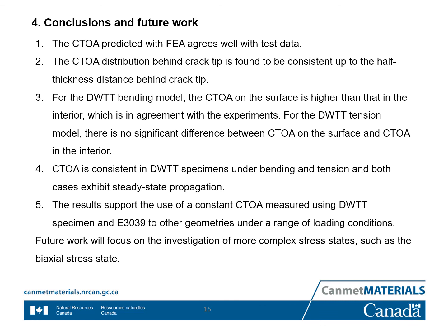Third, for the bending model, the CTOA on the surface is higher than that in the interior, which is in agreement with the experiment. For the tension model, there is no significant difference between CTOA measured on the surface and CTOA measured in the interior.